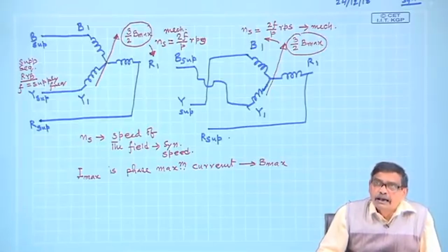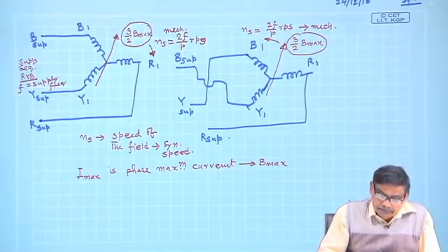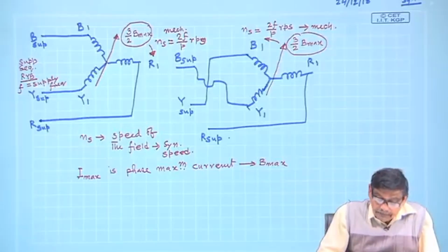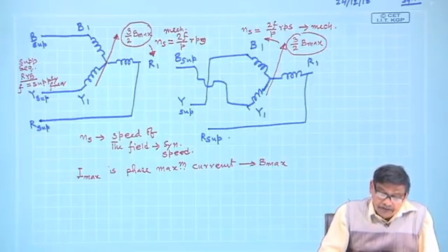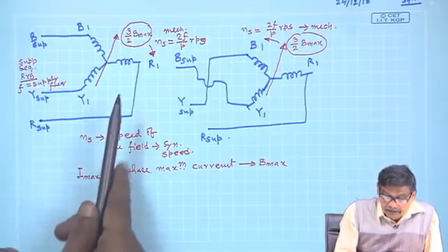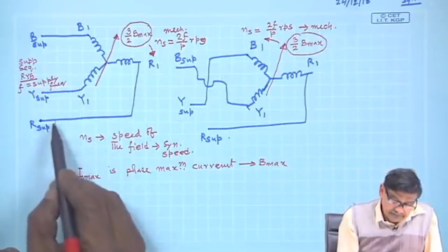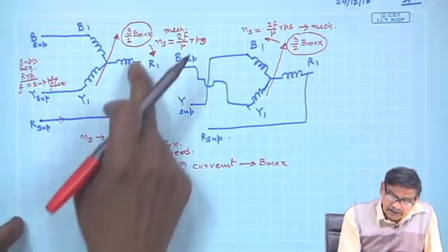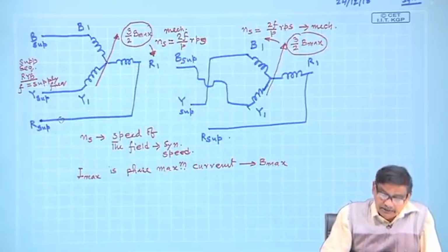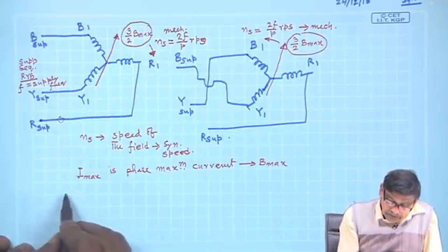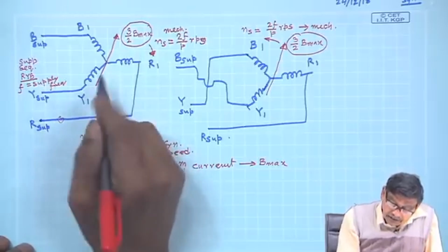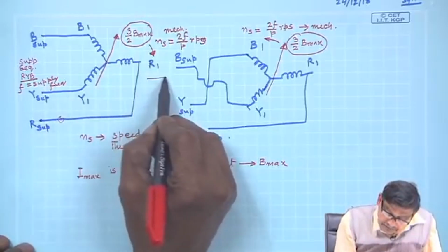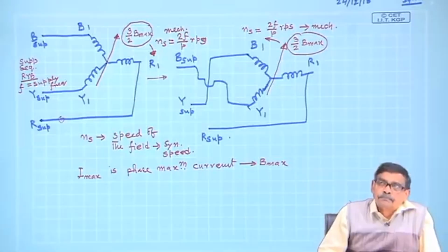But about one thing I am pretty sure, that is what I am trying to tell. What is that thing? If right at this point of time, these currents I can see in the oscilloscope, if the R phase current is maximum value I max, then I am sure the resultant field will be along the x axis. That is what I want to tell.